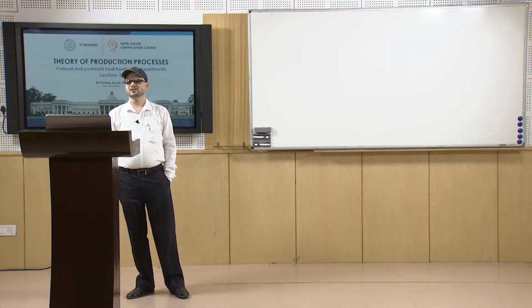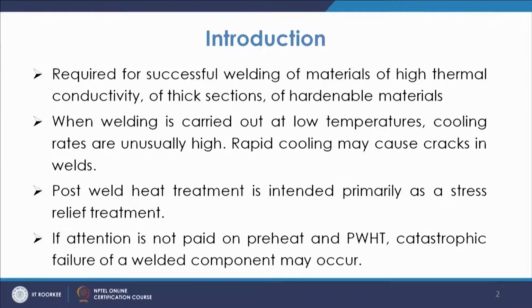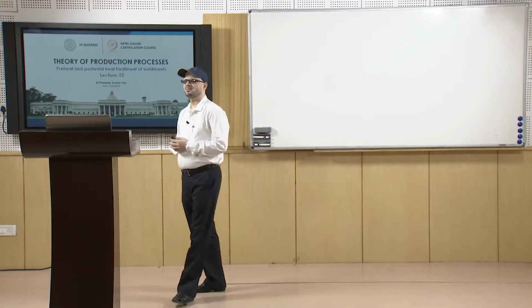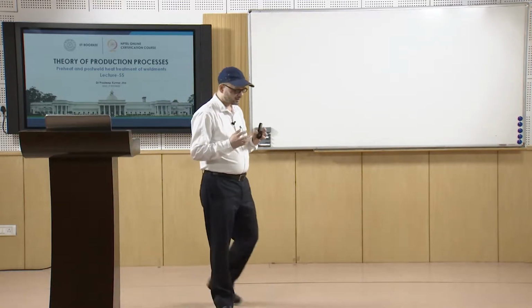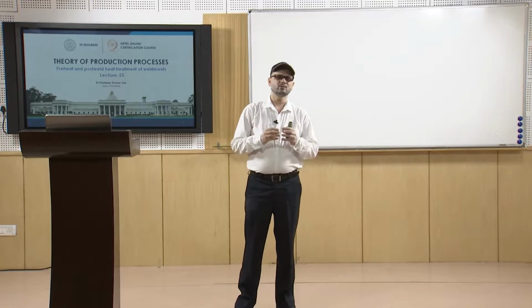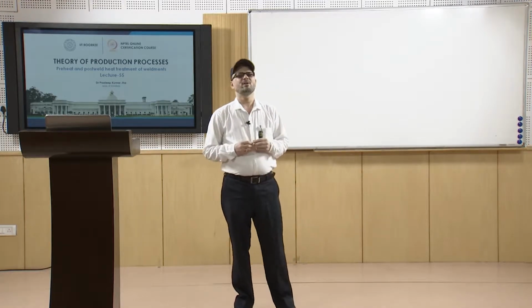They are required for successful welding of materials of high thermal conductivity, thick sections, or hardenable materials. Basically, the challenge comes with materials of high thermal conductivity. In those cases the heat transfer from the weld specimen goes very fast.